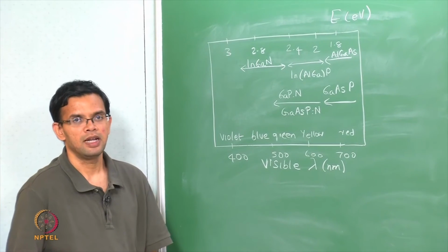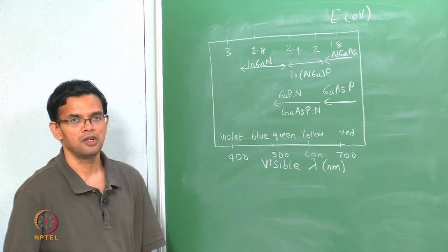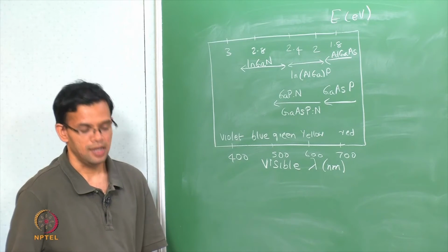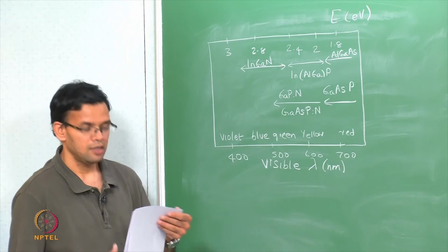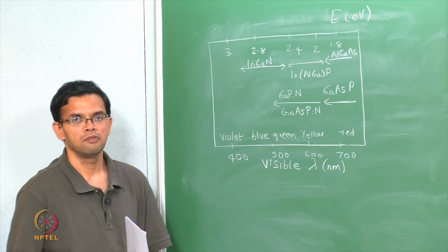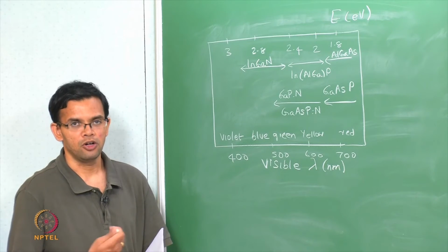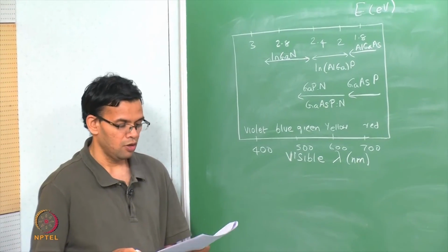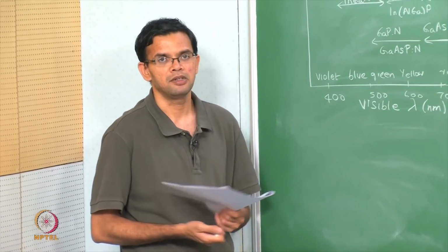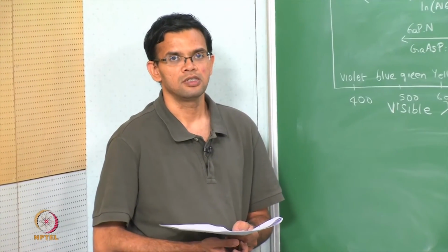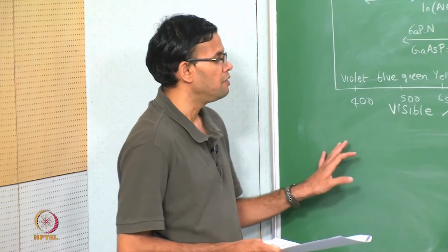Gallium arsenide is a direct band gap material, and you can also use it as a substrate for growing many of these LEDs. In order to avoid defects, these LEDs are usually grown by some vapor deposition means like chemical vapor deposition or atomic layer deposition, or even a simple physical vapor deposition like sputtering or laser processes. So, this enables you to grow different layers with minimum defects.